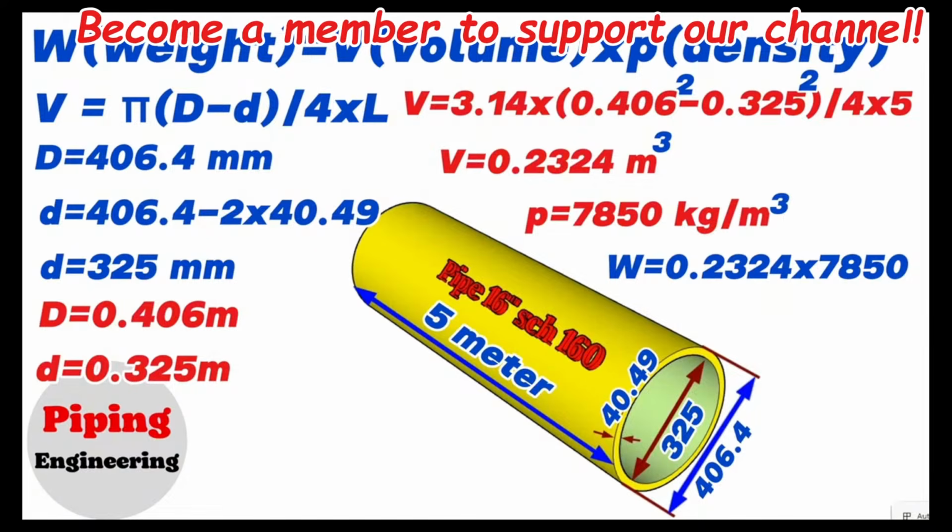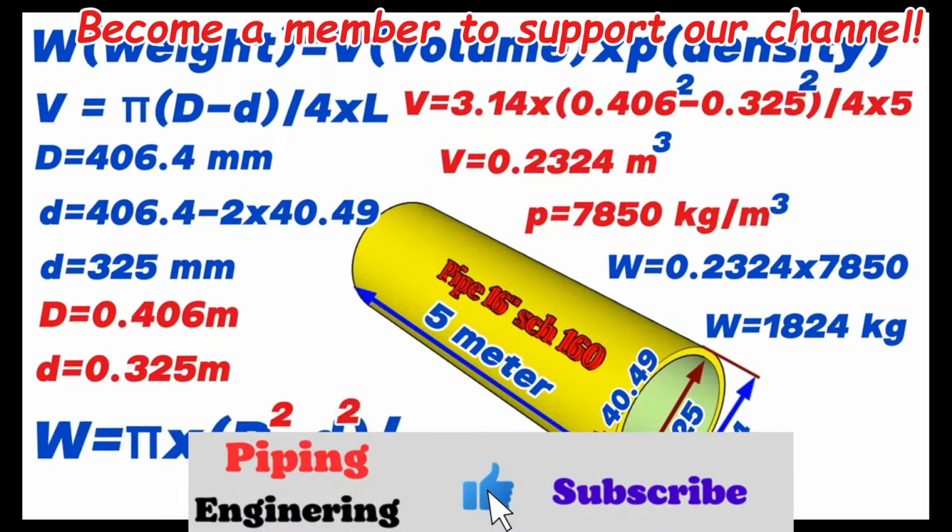Summarizing what we learned in this video, we can also use this formula to find the weight of the pipe. Weight is equal to pi multiplied by, in brackets, the squared outside diameter minus the squared inside diameter, divided by 4, multiplied by the length of the pipe and multiplied by the density of the pipe material. By using this method, you can easily calculate the weight of pipe pieces in any pipe drawings.